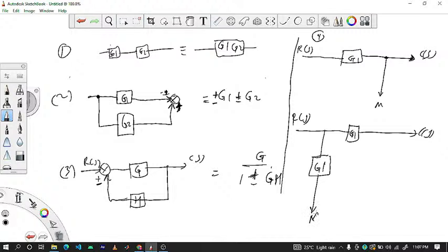You pass the line through G1 because that's all. If it were here and I was moving it to the other side, assuming the pickup point was here, and I was moving it here, I'll pass it through 1 over G1. So you can just learn that from after the block to before the block is G1. The other one is opposite. That's all.